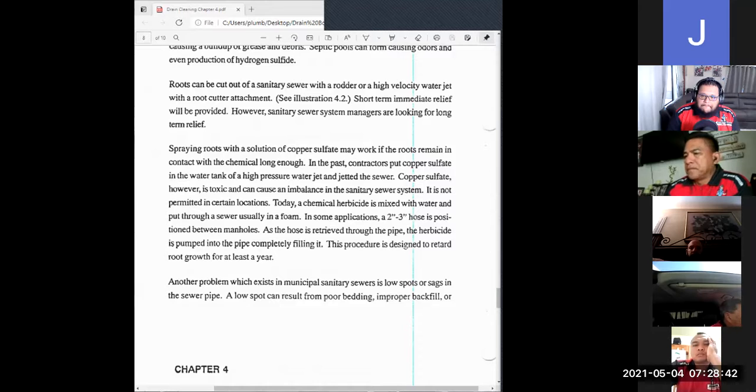And man, the size of the pump and unit that it takes to get into like an 8-inch line. When you start dealing with that, you're going, like you said, Bennett, from manhole to manhole. Like our class stated prior, manhole to manhole distances are usually about 300 feet. If you're 300 feet, 8-inch line, you have to assume the volume of product you need to consume that size of pipe requires kind of like a jetter. You're not going to use a brute jetter to jet an 8-inch line, right? You're going to take the larger jetter because of volume.